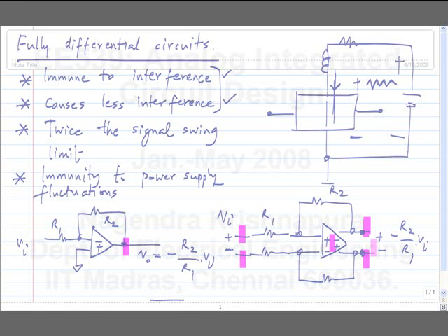Okay. The question was, how do you decide the sign of the op amp in fully differential circuits? Exactly the same as before. How did we decide it here? How did we decide the signs of the op amp in this case? What I do essentially is I assume some signs and calculate the input voltage of the op amp as a function of the output. Now, let's say I delete the input signs. I don't know what it is. I assume some signs and calculate the input difference as a function of the output. Okay, it should be in opposite phase to the output. So that finally,